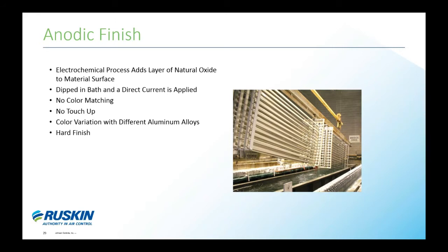Disadvantages of the anodized finishes include color selections limited to clear and bronze hues, shorter warranty periods, touch-up trouble since it's chemically applied, and color variation will most likely occur if the sunshade uses different aluminum alloy types. That last sentence is very important when using sunshades and anodize.